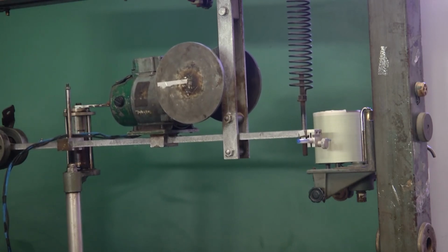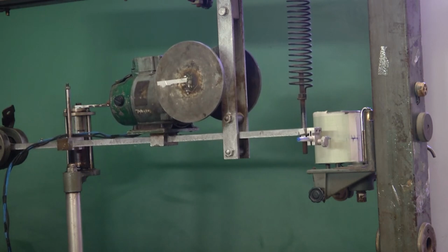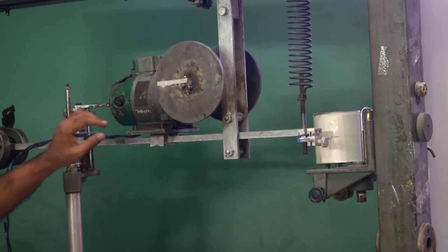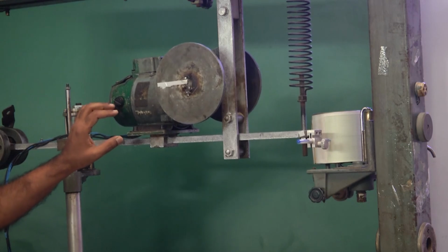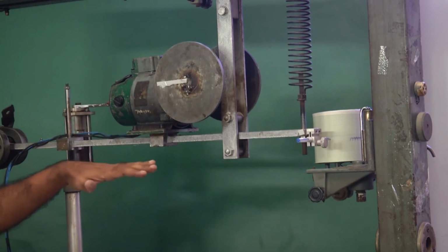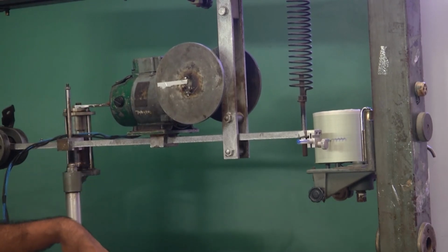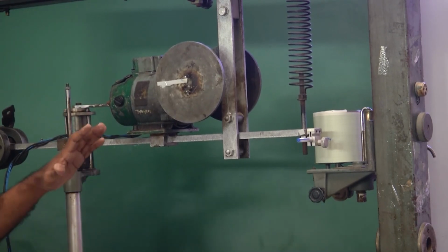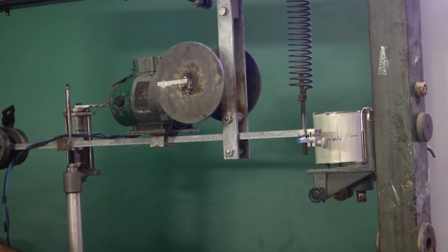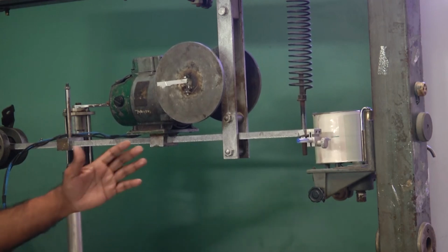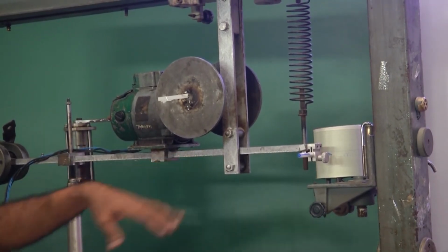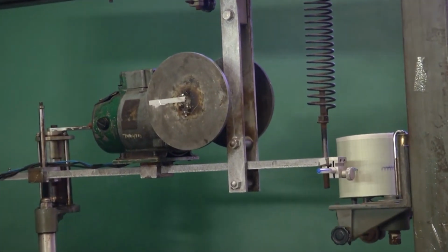Now, we will of course be interested in not only knowing the natural frequency of the system, but it would be interesting to also estimate or extract the damping parameter. Okay. Now, you may notice that although I have disturbed it with some amplitude, the amplitude is gradually reducing, and it will come to 0 after a while. Obviously, there is some amount of damping in the system which is causing the amplitude to continuously reduce over a period of time.